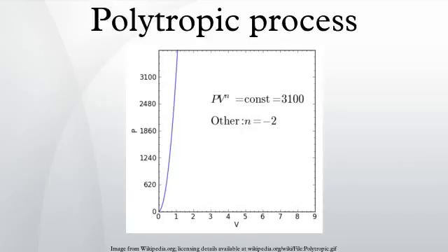Polytropic specific heat capacity is denoted by c_n and it is equal to the following. Relationship to ideal processes. For certain values of the polytropic index, the process will be synonymous with other common processes. Some examples of the effects of varying index values are given in the table. When the index n is between any two of the former values, it means that the polytropic curve will be bounded by the curves of the two corresponding indices.